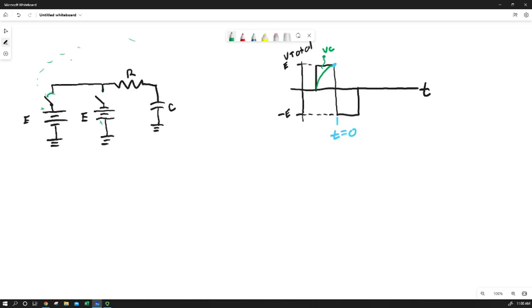Then we looked at the effect of that closure, the current flow, and the time-dependent charging of our capacitor, to get an expression for what we would see on our oscilloscope if we looked at the voltage drop over the capacitor. If we took this measurement in a circuit that we built and plotted it, what would we see? We derived a nice expression for time-dependent voltage as an exponential function of time, with RC equaling the time constant.